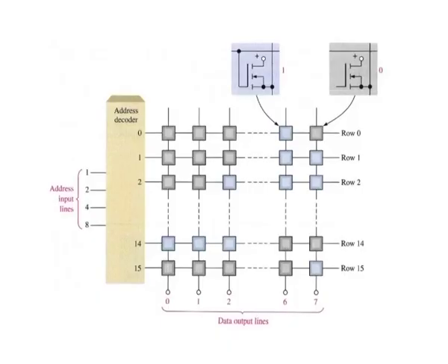A simple ROM. To illustrate the ROM concept, figure shows a small simplified ROM array. The blue squares represent stored ones and the gray squares represent stored zeros. To understand the basic read operation, let us assume that when a binary address code is applied to the address input lines, the corresponding row line goes high.